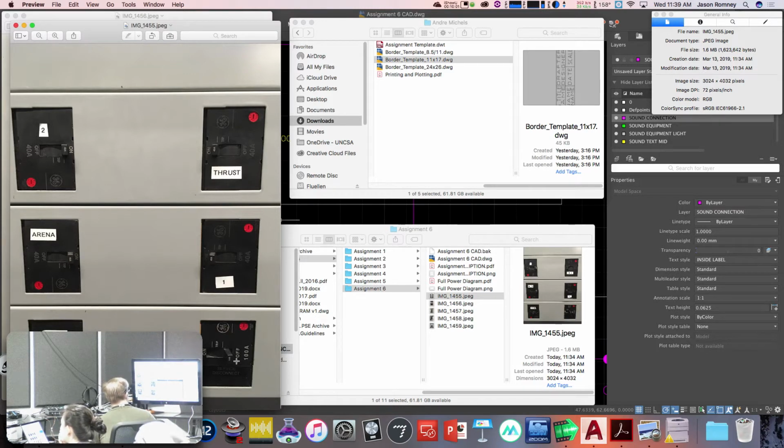So in total, there's a lot that is going off of that 400 amp service. If each of these is actually 40 times 3, what's 40 times 3? 120. So 120 times 1, 2, 3, 4, 5 is what? 600, plus the 100 on the service disconnect. So 1, 2, 3, 4, 5 times 120 is 600, plus the 100 amp disconnect, 700.